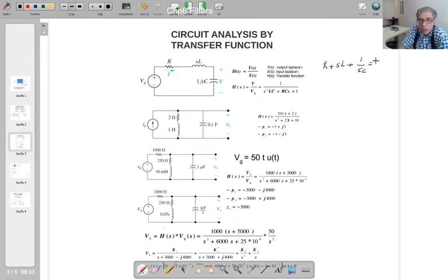That is the equivalent impedance. So if I divide VG by this impedance, R plus SL plus 1 over SC, I'm going to find this current here. Since these elements are connected in serial, this current is also the current of the capacitor.